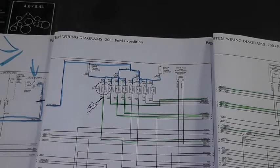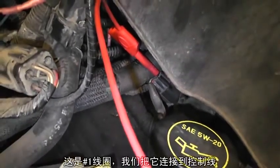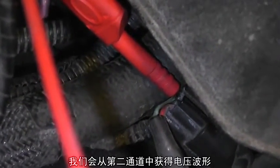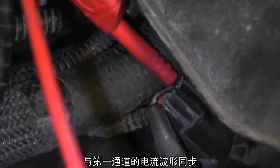Well, actually, let me get a shot of where we're connected, and then we'll go and show you what it looks like up on the board. Okay, this is the number 1 coil, and we're connected to the control wire, and we're going to get a voltage waveform on our second channel, and again we're going to synchronize that with our current waveforms on channel 1.